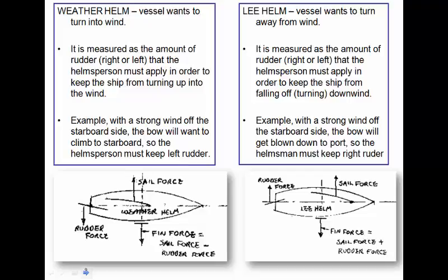So if I have a vessel whose pivot point, so here we're going to use a barge, and let's say I have a pivot point here, but its sail area, and this will be the bow in this case, its pivot point is here, but the centroid of its sail area is actually back here. Well, the wind is going to want to push my bow in this direction or back into the wind.